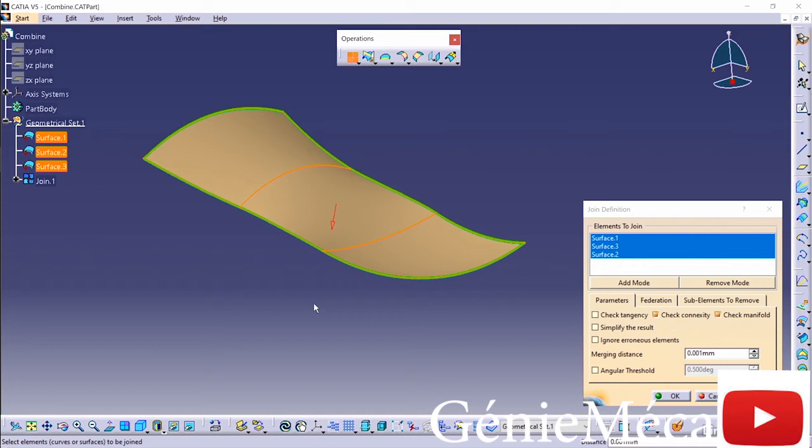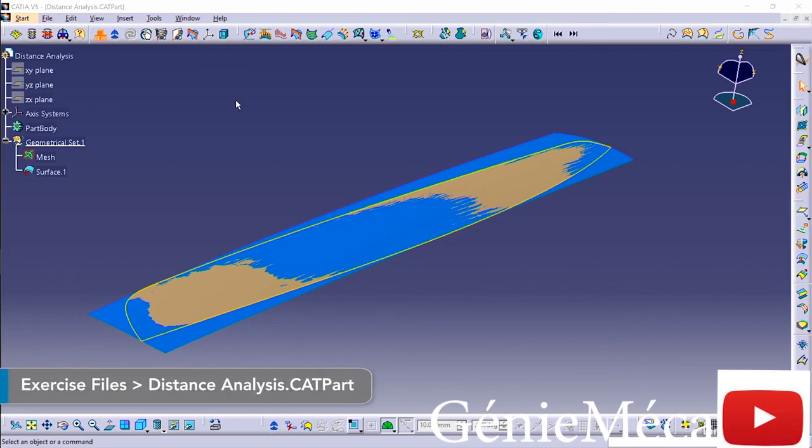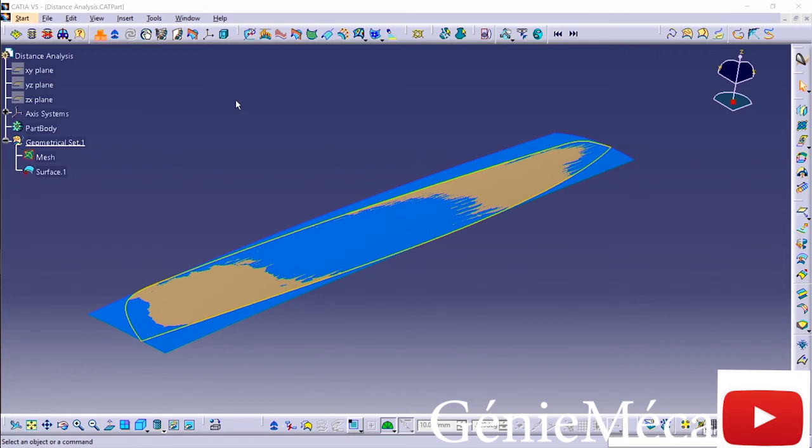And this is a really good way of taking several elements all at once, joining them, making them one, and then forcing the normal to go in the direction that you need. As you're going through and creating your surfaces through your reference data, whether it's mesh data or curves, or whatever that may be, you want to verify that the data that you create is within tolerance to your background data or your input data.